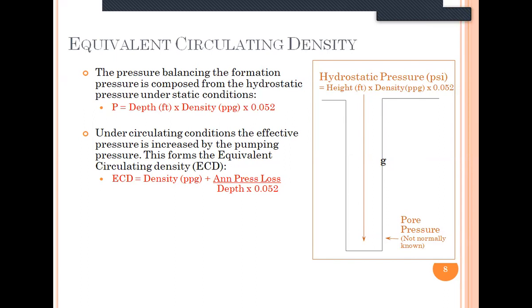This fluid is called high performance mud, especially when you have a very long lateral section and a problem of ECD, which will be a very serious problem for you. So the ECD, you cannot neglect it. Maybe you want very good hole cleaning. Okay, increase the viscosity. Hey, stop. If you increase the viscosity too much, you will have too much friction and produce too much ECD. This is not the good way.